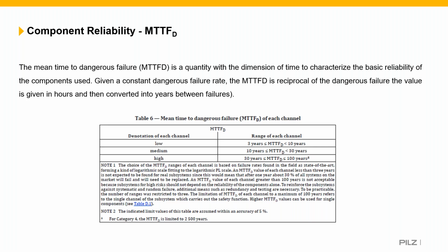One thing to just be aware of is that if a manufacturer does publish this data, it will be based on a number of operations. And you've got to make sure that you're not going to exceed this. So if a door's being opened frequently, a contactor's going in and out very frequently, then actually you might exceed the data which it's stated, and therefore that could reduce your MTTFD.